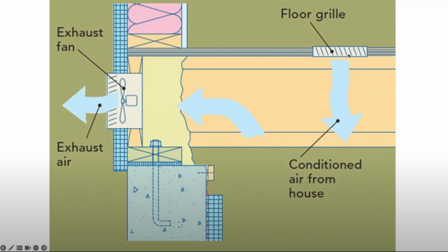So, when we talk about thermodynamics, the second law, where high goes to low, if we're exhausting here, then we're going to be pulling air into the attic area. This potentially brings in hot, humid air from the outside into the upper levels of the living space, and then pulling the air through the rest of the living space to exhaust. We typically don't want to create that type of negative pressure. This is especially true in hot, humid climates where we commonly see crawl spaces. When you come across these types of homes and check the RH levels in the spring, summer, or fall, you will likely find high RH levels.